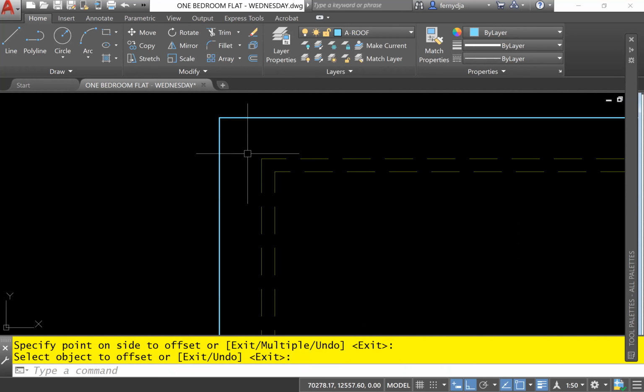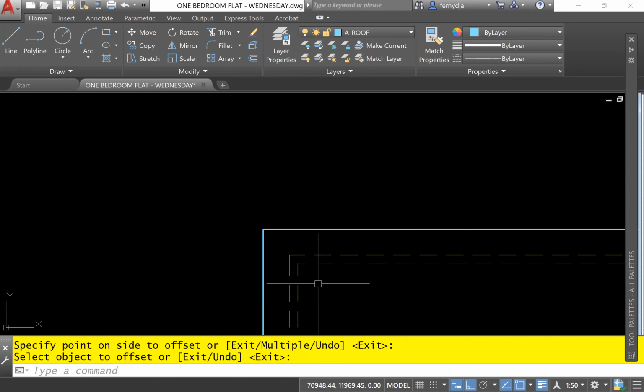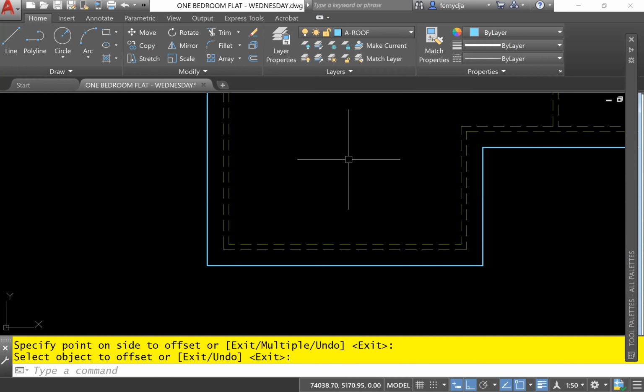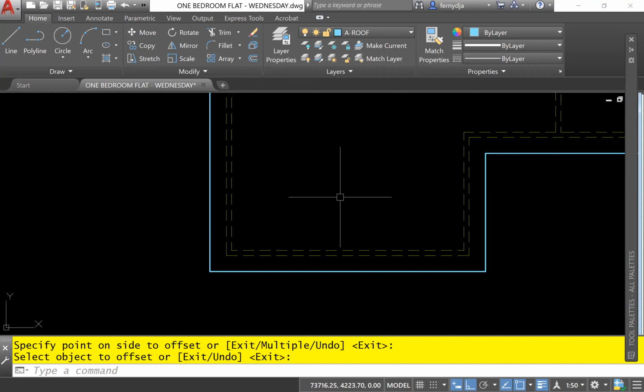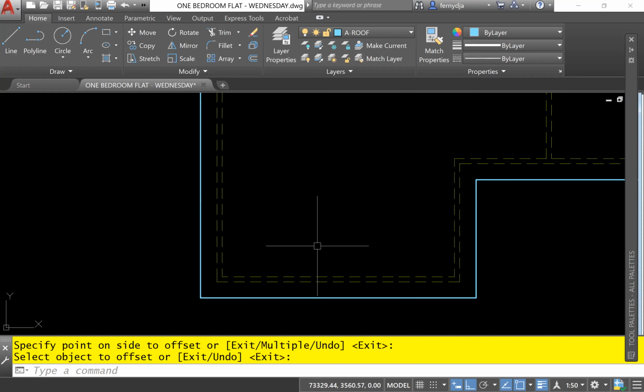Now that represents the outside edge of the fascia. So later on, I'm going to offset 25 millimeter in, but to keep it simple, I'm not going to work with the two lines right now. I'll put in that line afterwards. So let me zoom in at this corner of the building, this end, and then I'm going to now start putting in my hip rafters.